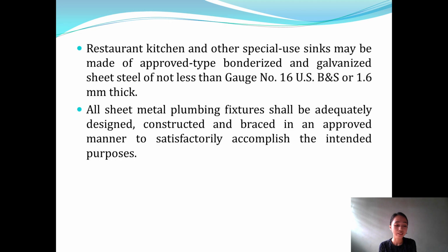Plastic materials, although generally durable in themselves, are readily prone to surface damage such as scratches and cuts. Stainless steel is a preferred material for plumbing fixtures where there is a risk of damage from users, such as in institutions and public amenities. Stainless steel is currently the only suitable choice in commercial or industrial food preparation areas.